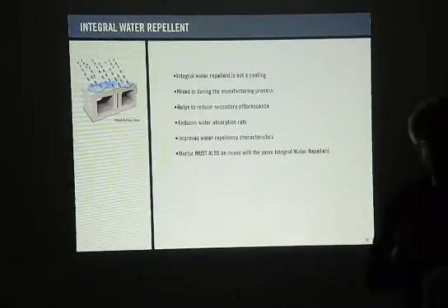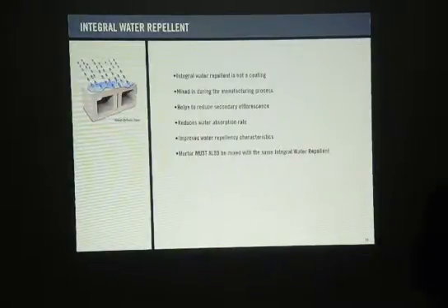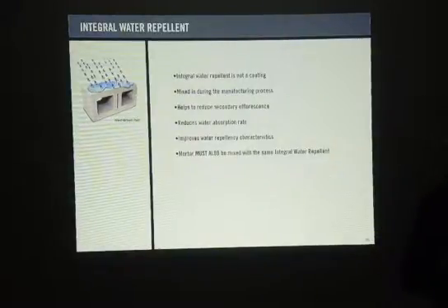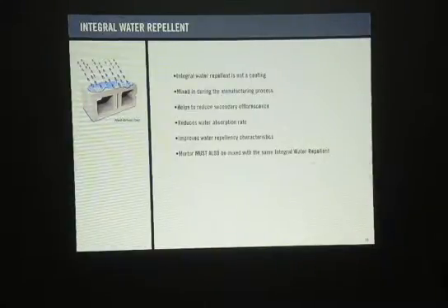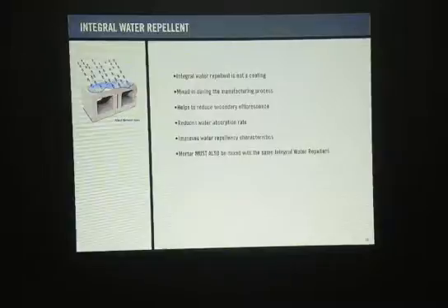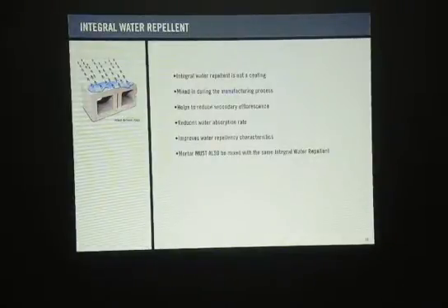But I'll also say, not only do we want to do the block, we also want to do the mortar for it, okay? So the mortar also needs to be with an integral water repellent. So what does that do? Does it waterproof, Mike? The answer is no, it does not waterproof. Is there an increased cost? Yes, there's an increased cost. But it gives your client better peace of mind because they don't see that unsightliness of efflorescence, okay?